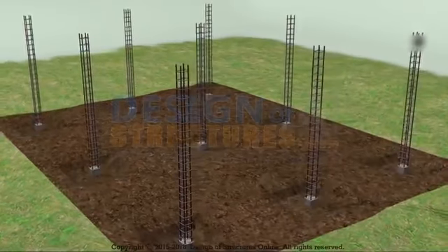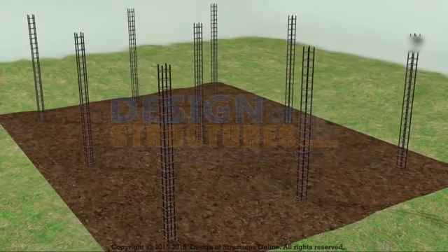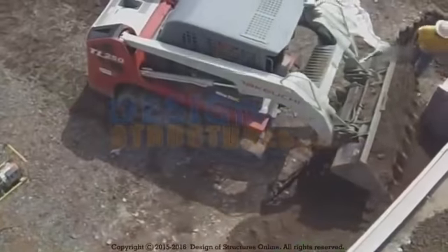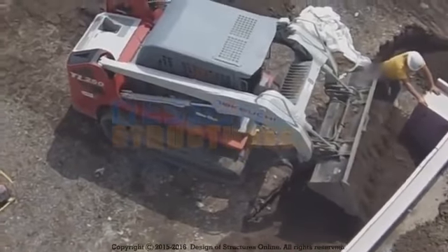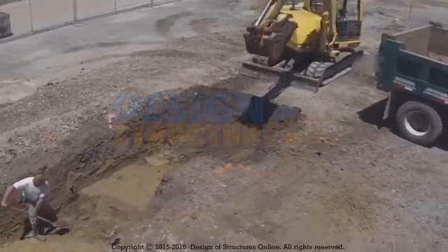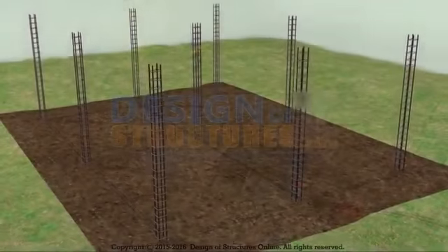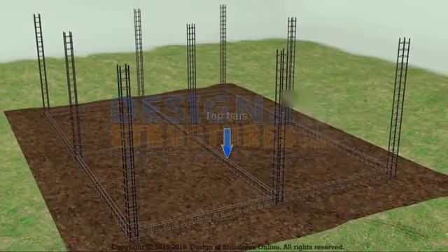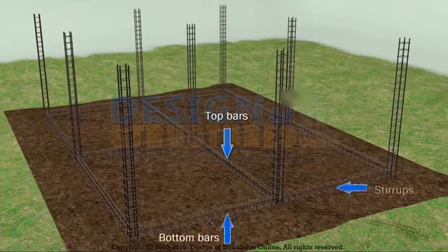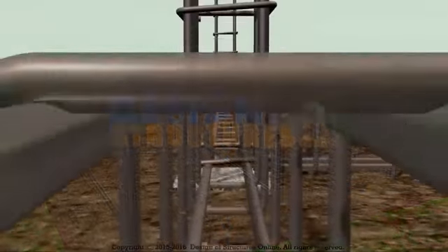Backfilling. Once the foundation is completed, backfill the remaining excavated area around the foundation with soil. Backfill provides stability to the building. Plinth beam over foundation. Beam reinforcement shall be as per drawings. Top bars, bottom bars and stirrups to be placed with proper development length.